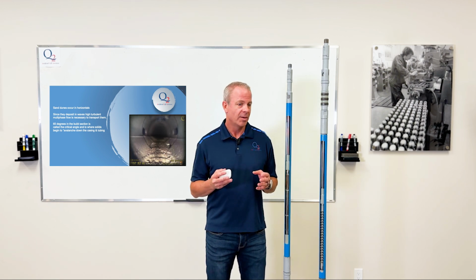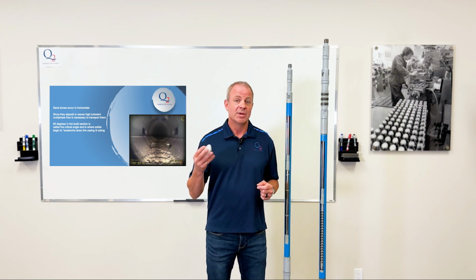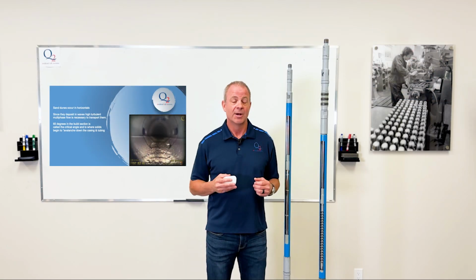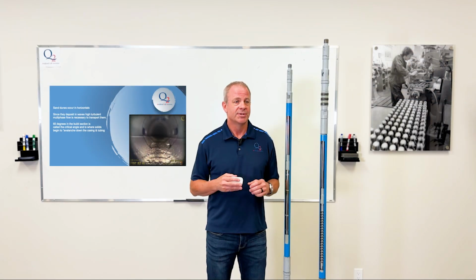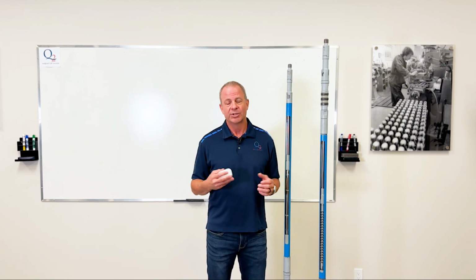Now when it comes to solids, we always try to get more data from our pump shops. When a pump comes in and say it is plugged with solids, the first thing we do is meet with the client and ask, what were the operational procedures? What's the overall solids strategy for fracking these wells? Is it native? Is it frac sand? Is it sand that's used to prop the fractures open downhole to create more permeability from your fractures? And do you run liners? Do you do clean outs? So we ask all this information.